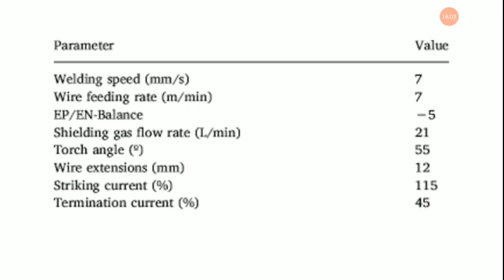In multi-response, the analysis of means establishes that a combination of higher levels of peak current, base current, and gas flow rate, and lower level of welding speed, and intermediate level of pulse on time and frequency is essential to achieve simultaneous maximization of penetration and minimization of face width and back width.